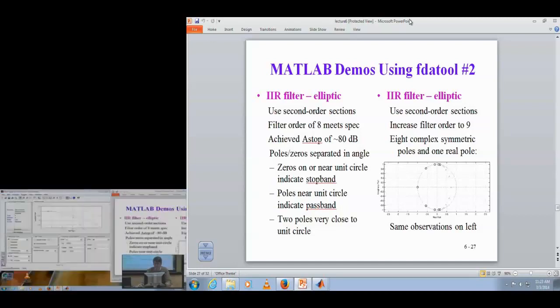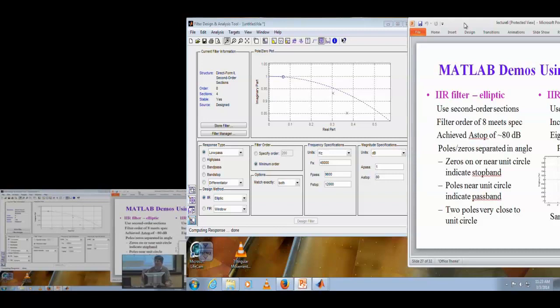Now, that constraint may mean that the filter order has to increase, but, which is not intuitive, we can get a 10th order filter that's easier to implement than an 8th order filter in terms of stability after implementation. It's more complicated because I have 2 more poles. There are more multiply-add operations per sample, but the trade-off is it's less likely to go BIBO unstable when implemented.